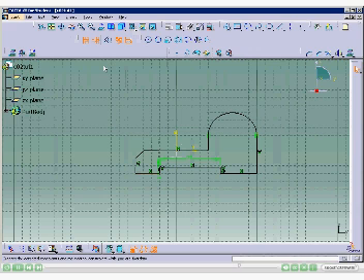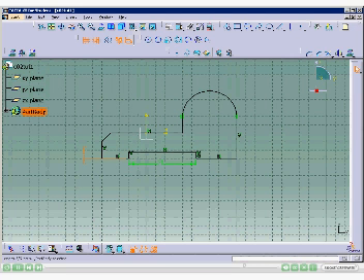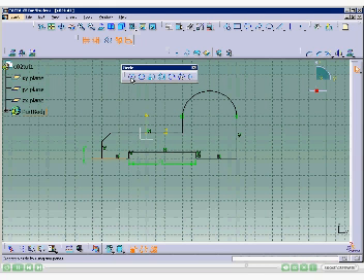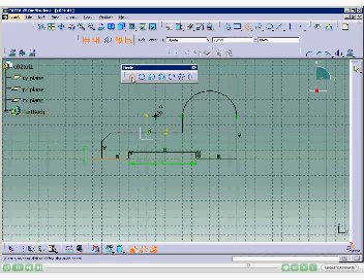It is recommended to modify the geometry area such that the sketch fits inside the screen. This is done by using the Fit All In tool. Arrange the dimensions properly by holding their arrowheads. Next, you need to draw the circle. To do so, choose the Circle button.